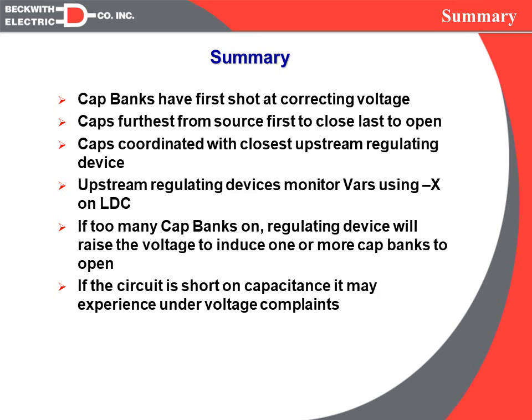We also are going to coordinate our regulating devices with our capacitor banks in the case that we get too many capacitor banks on, correcting the voltage and driving us into too far of a leading condition. In that case, a negative X setting in the line drop will induce the regulator or the LTC to raise the voltage, therefore inducing one or more capacitor banks to open.